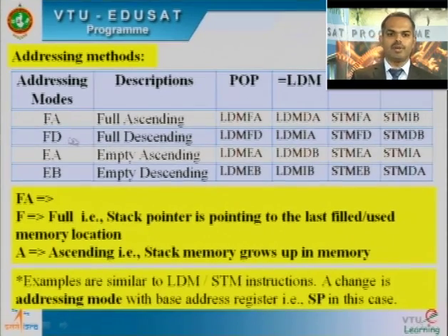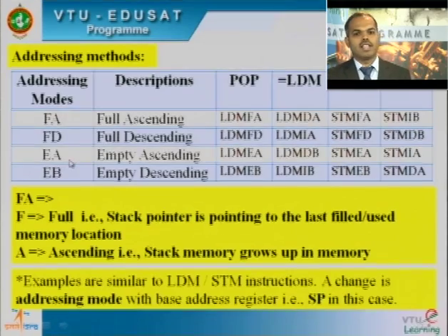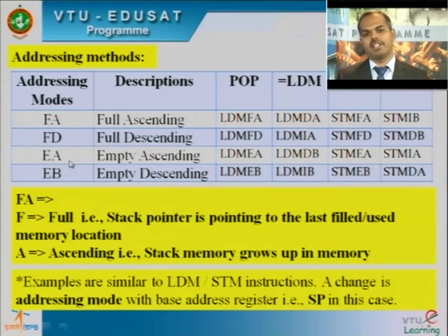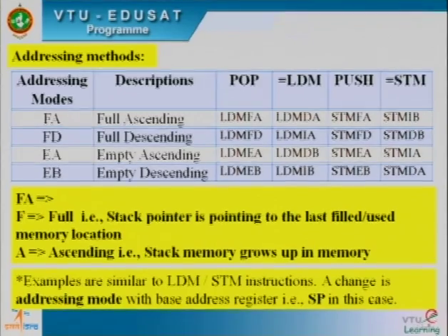Similarly, there is a full descending stack, empty ascending stack and empty descending stack. So what you have to remember here is that the stack can grow up, the stack can be ascending or descending. The stack pointer can point to the last empty memory location or the last filled memory location. If you remember these 4 concepts, then understanding addressing modes will be easy.